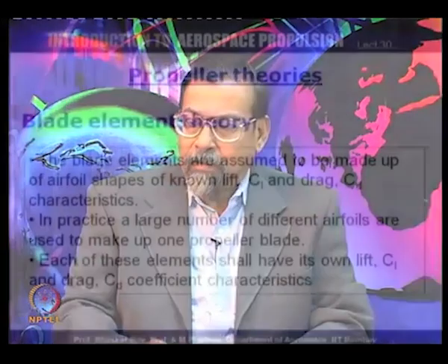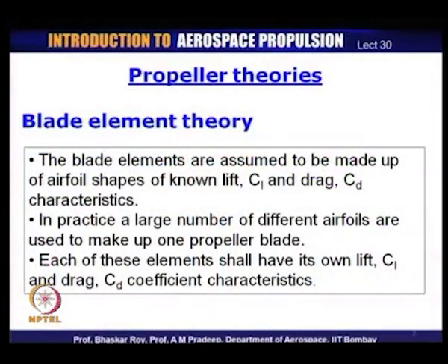So, let us take a look at the propeller theory that uses the propeller blade shape as it actually is, and the aerofoil sections, which actually provides the conversion of lift and drag to thrust and matching of the torque that is provided by the engine. The theory that uses the propeller blade shape is simply known as blade element theory. There are of course, various versions of the blade element theory. We will be doing the elementary version.